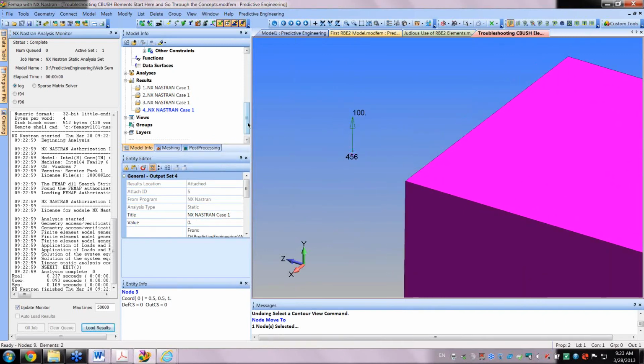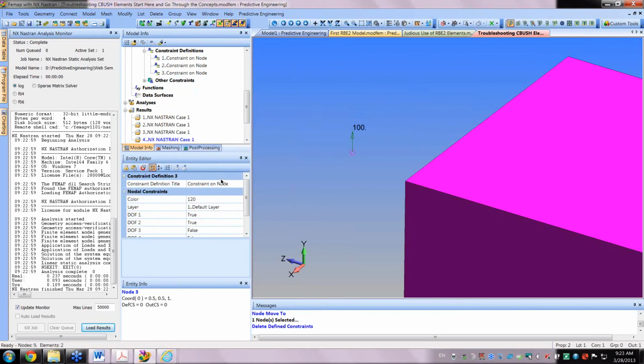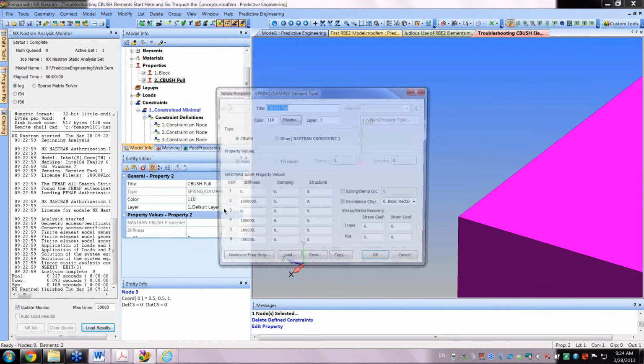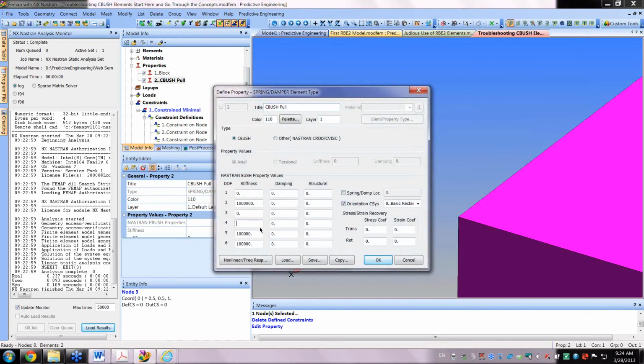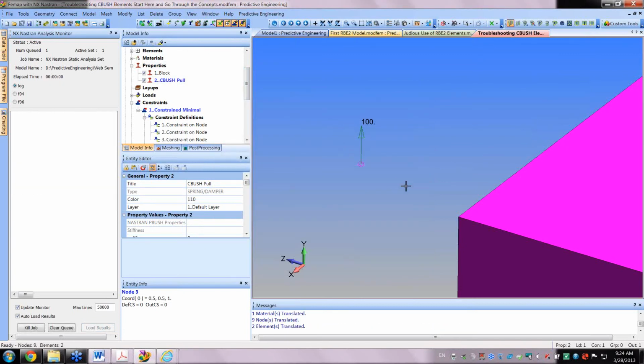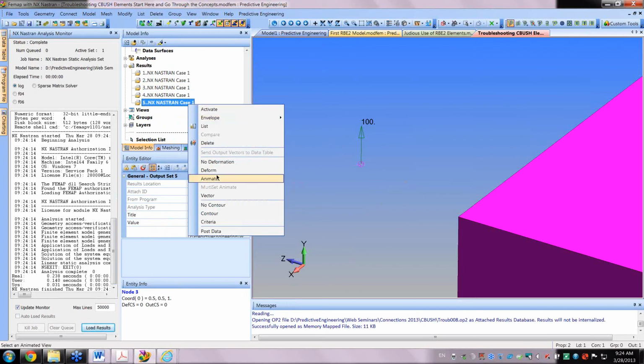Now look what happens. If they're coincident, I think some people are going to know, if it's coincident, you can't develop any moments. No moments are going to be developed because they're coincident. You don't need any stiffness in it. And it runs. No moments, no harm, no foul, coincident, voila. Just like a CELAS.